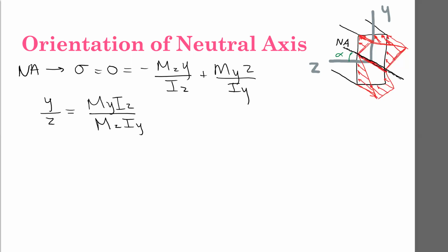Like when you're multiplying by z and y, are these like length? They're the distance from the neutral axis. You're measuring the distance. So if we want the maximum stress, remember we measured all the way to the extremity of the cross section. But if we're just interested in the stress at a particular location, we would plug in that y or that z value.